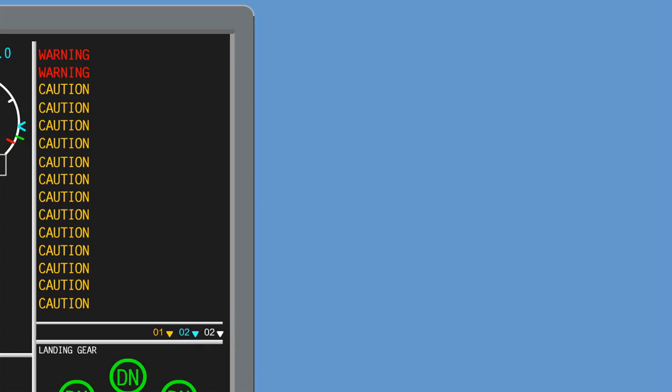The out-of-view message display includes the number of messages of each level, distinguished by a color, and an arrow indicating the direction of messages of each level, above or below the current window. The out-of-view message display, digits and arrow, flashes when there are unacknowledged messages out of view. The right out-of-view messages display represents the number of messages out of view below the displayed window, while the left out-of-view message digits represent the number of messages out of view above the displayed window.